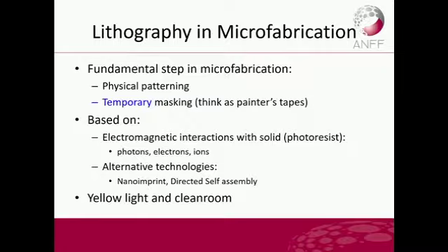Think about patterning things down to, say, less than 50 nanometers or even 20 nanometers. And the acceptance, if you talk to the IC industry, is that they will not accept any devices with more than one defect per square inch. When you make a 12-inch wafer, they will not be happy to have more than one or two devices that actually failed from your lithography processes. So clean room is very important.